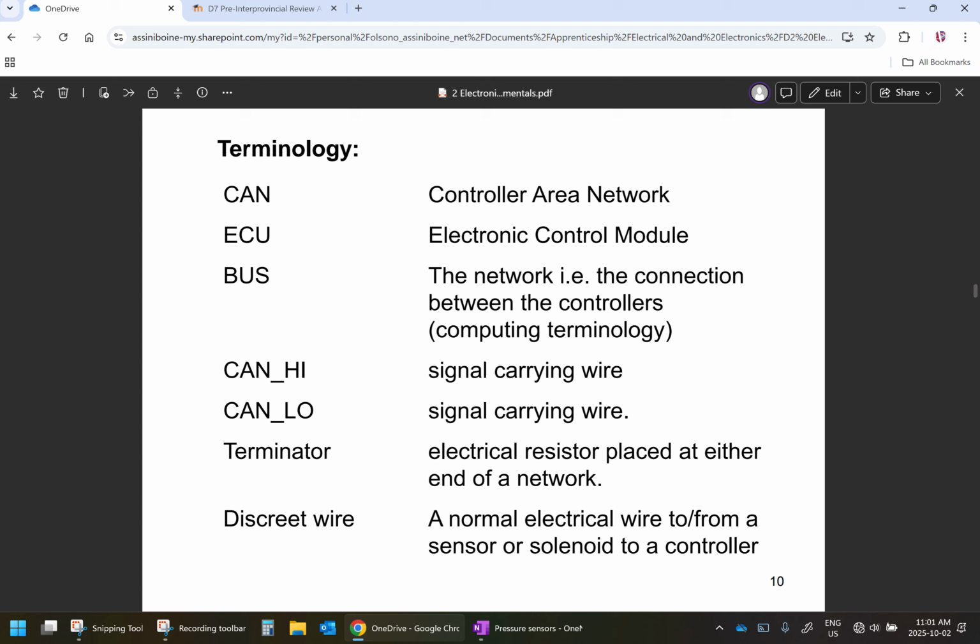If you have a machine and you have two physical terminators on the machine, and you're measuring the resistance and it shows you 40 ohms instead of the 60 that you expect, does that mean that there's a short somewhere in there? Not necessarily. Okay, I have seen and I've heard of instances where one manufacturer building a machine puts a third-party engine in that machine. If they buy an engine that was designed to be a standalone power unit engine, it probably already had a terminator built into its ECM. And then that manufacturer puts their own CAN bus network with two terminators on the machine. So now you effectively have three. Okay, it's something to be aware of. It's not super common, but it can happen.